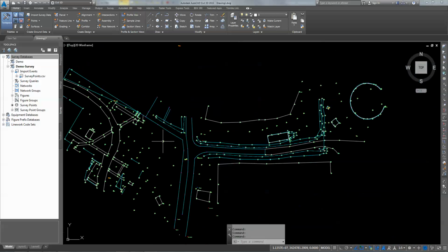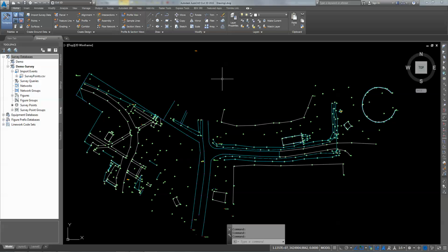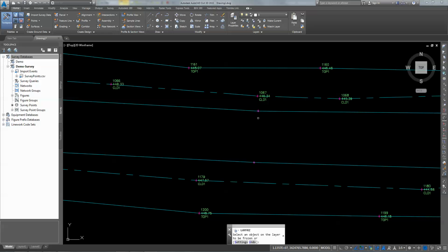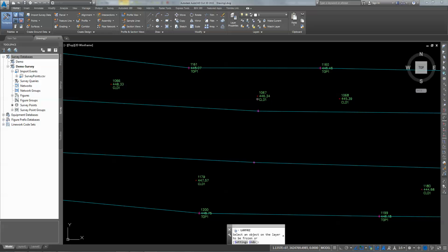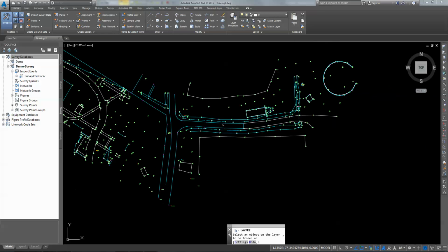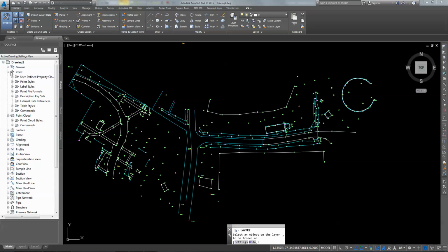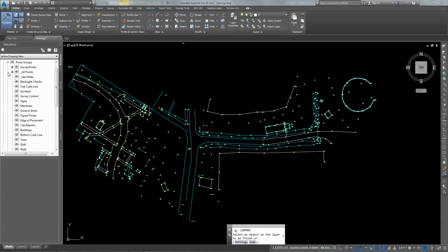You can see the points here in the drawing as well. And to remove those, I can come in and I can freeze the layer in this case, where I have to come in and choose it. Now at layer, let me see here. So you can see these layers are a little bit different. It's a little bit harder to freeze those, and that's just probably because of the style. But there are ways to turn those off, such as going to settings and prospector and point groups.